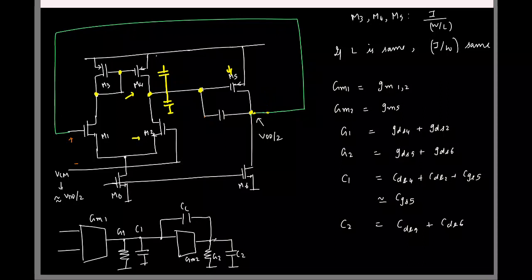So now in addition, you can also have the load capacitance and load resistor, so you can connect it. So load resistor, let's say we have RL. From the output we'll connect it. And what about the other terminal? Where will you connect this to? Okay, so if you connect it to ground, at DC, this is at VDD by 2. So this will start drawing a current and it will disturb all your biases. So where do you think I should connect this to?